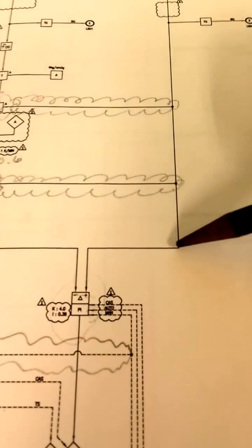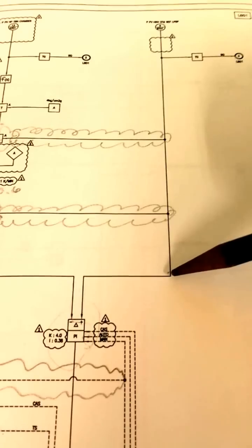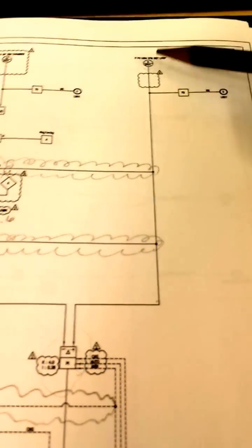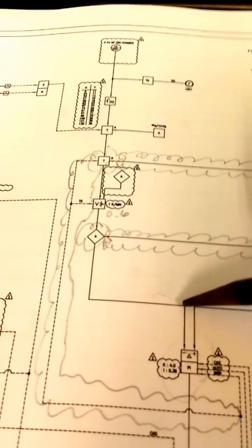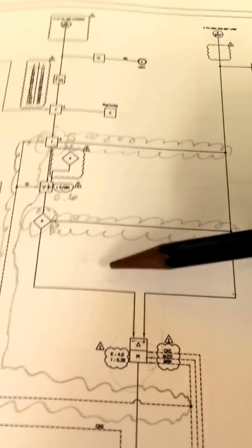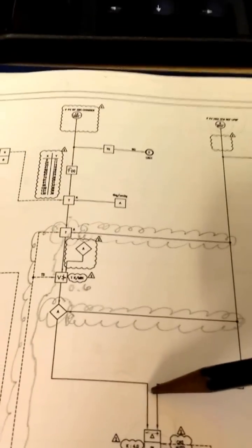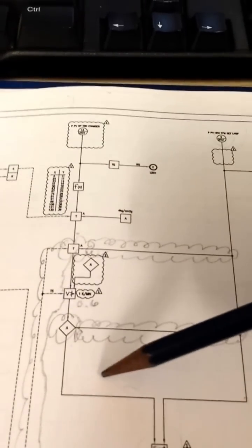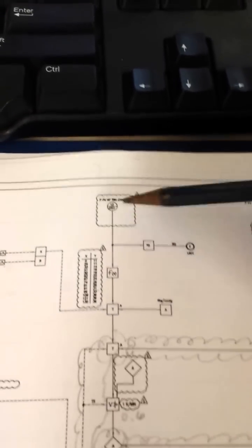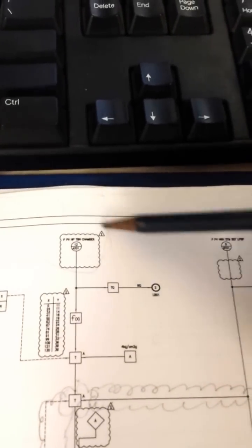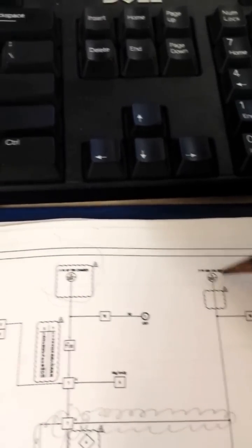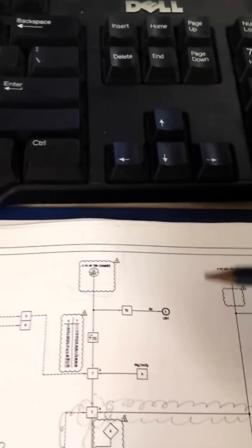Now here, this line is coming from the process variable, the signal coming from the pressure transmitter on the process line. The other line is the set point. Usually the set point is a fixed value, but in this particular control, the set point is not fixed, but rather a value coming from another pressure transmitter from another line. This line and this line are not the same. They are different, but interrelated.